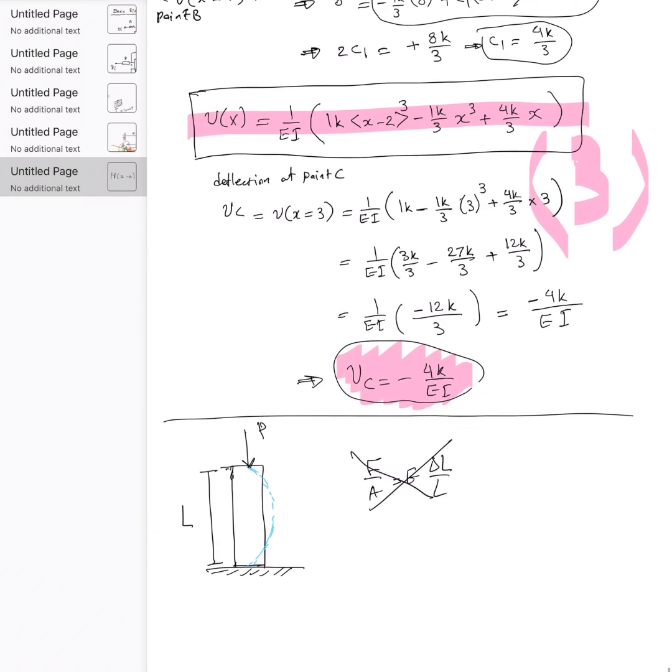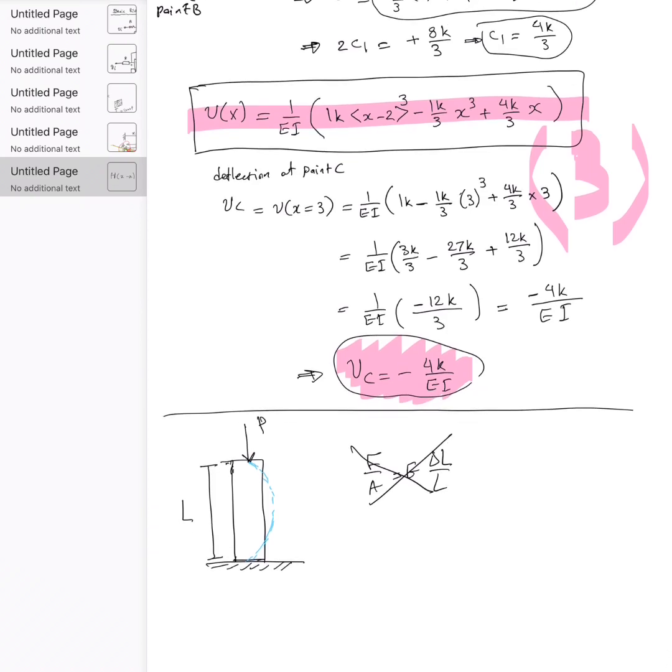So now the question is, if this is my design equation that I use to do a lot of things, I want to know when this equation is valid. Well, we already discussed it. This is only valid in the proportional region or linear elastic region. And you know that.